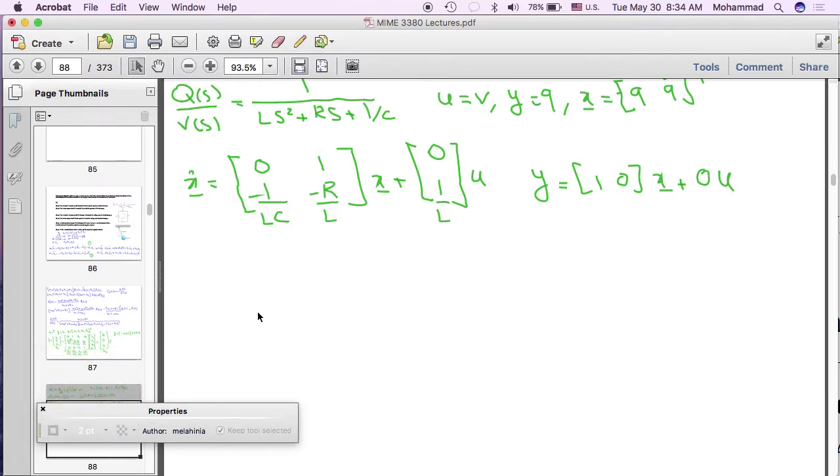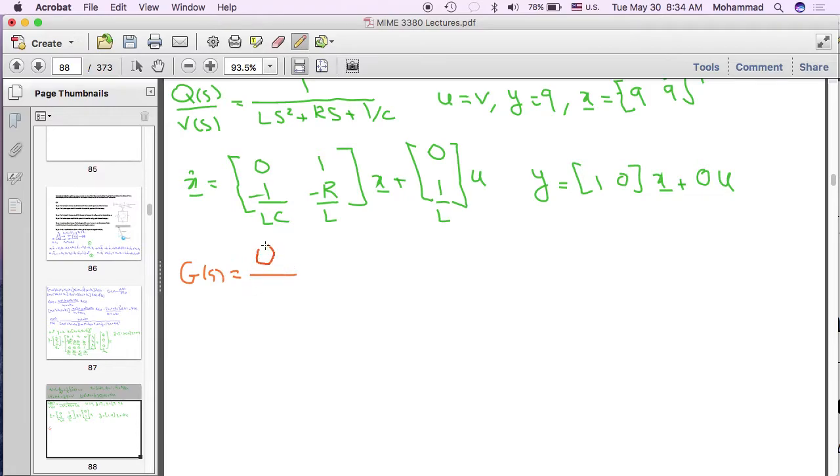So the next question was on a transfer function model for the pendulum. It specified the input as a torque applied. It also specified that there was friction, and we are looking for a model between the applied torque and the output angular position. So that means the transfer function that we are looking for, G(s), is between theta(s) and T(s), where T(s) is the applied torque. That's what we are after as the end result.